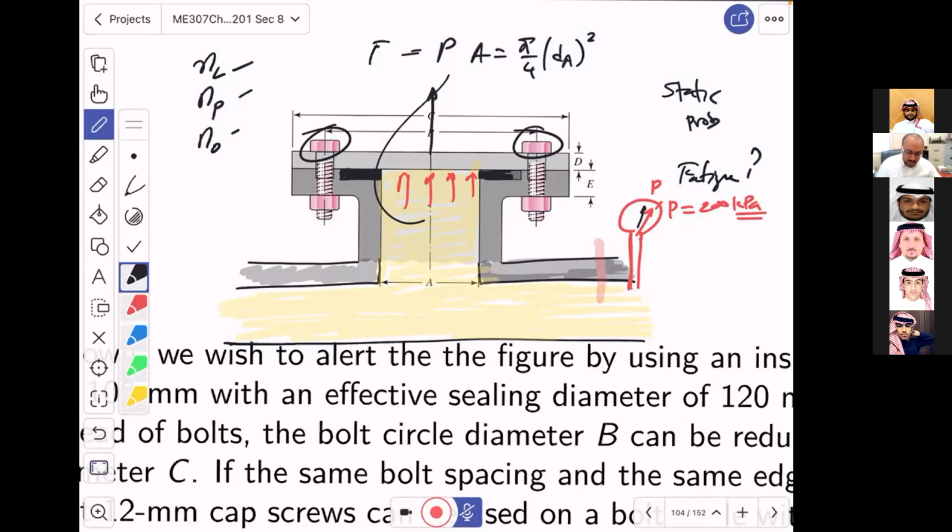And in the end of the day, you may see this pressure gauge going a little bit up and down, but within a controlled fashion. So the process engineers, like chemical engineers, will come and tell them, listen, you need to maintain the pressure between 290 to 310 kilopascal.